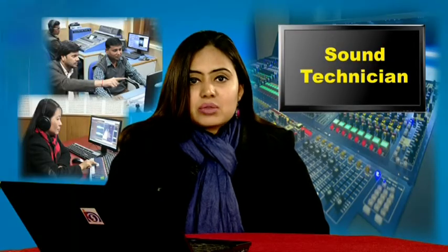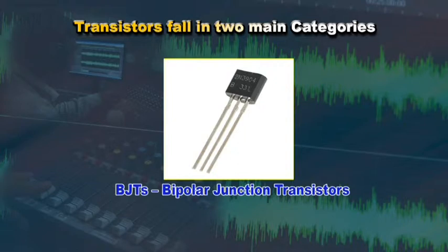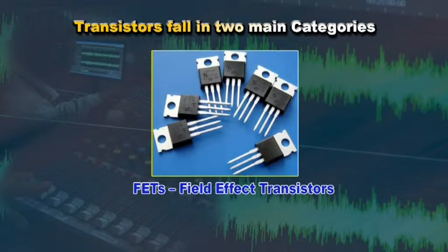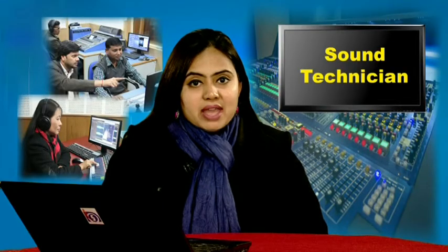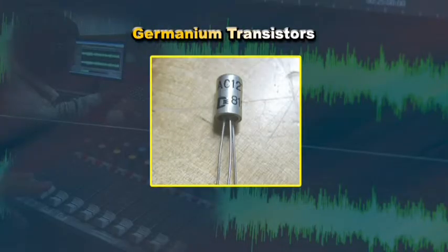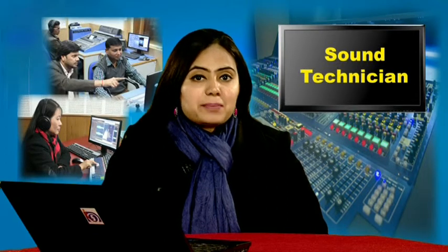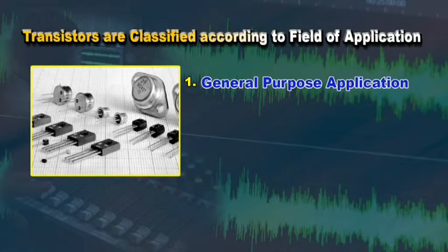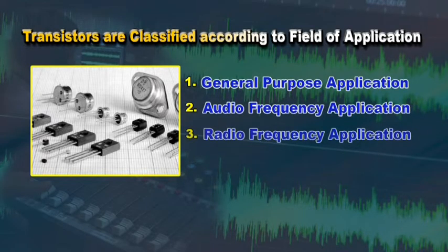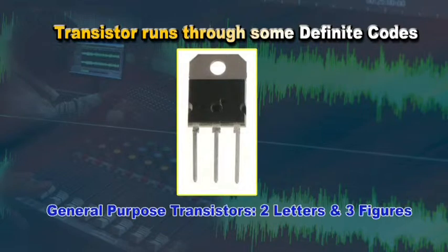One should also study the active components of the equipment. Transistors. Transistors fall in two main categories. First one is BJTs, that is bipolar junction transistors, and second is FETs, that is field effect transistors. They are also classified according to semiconductor material used, that is silicon transistors and germanium transistors. Transistors are also classified according to their field of application, like general purpose application, audio frequency application, radio frequency application, switching application.